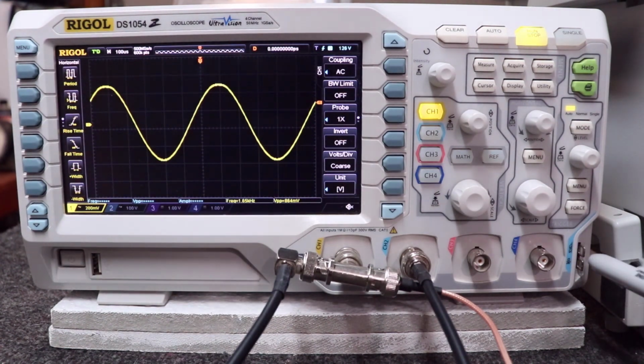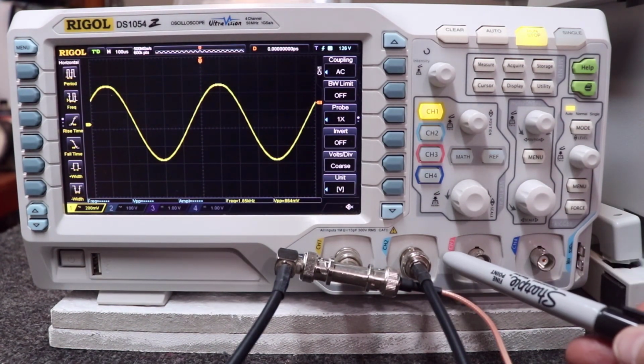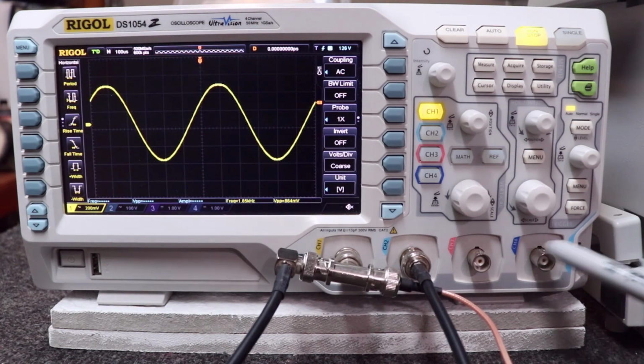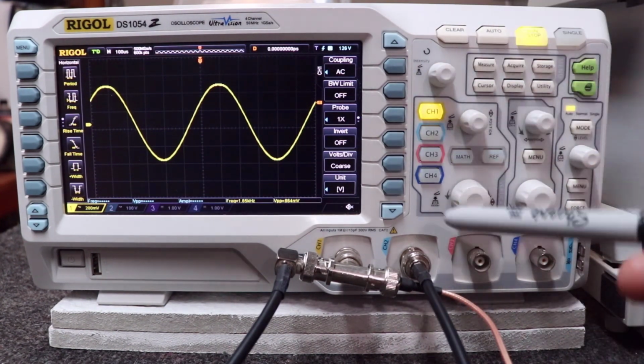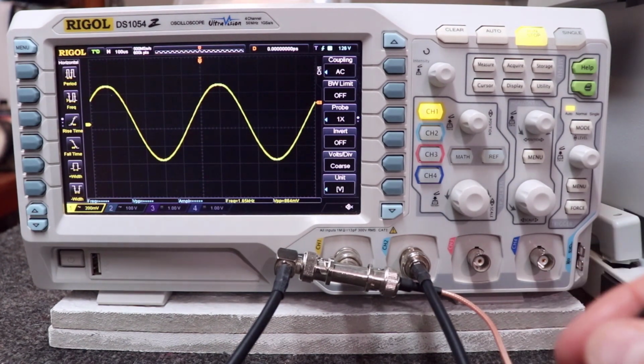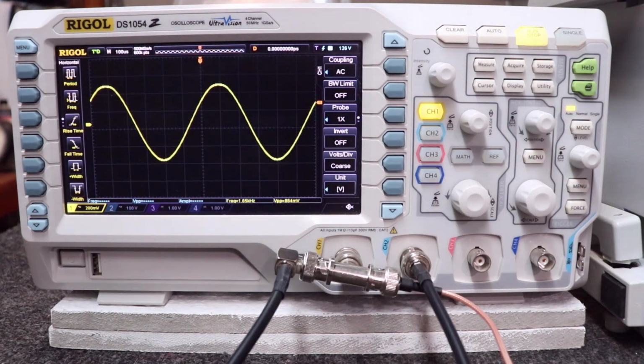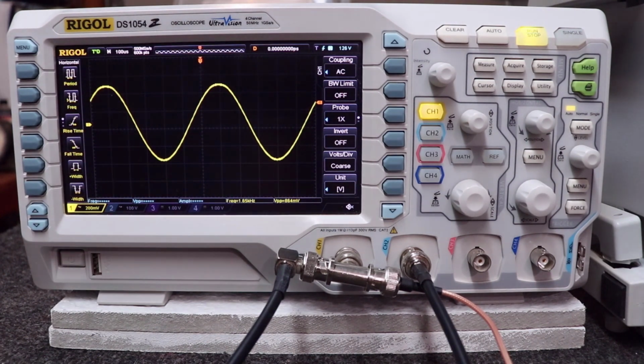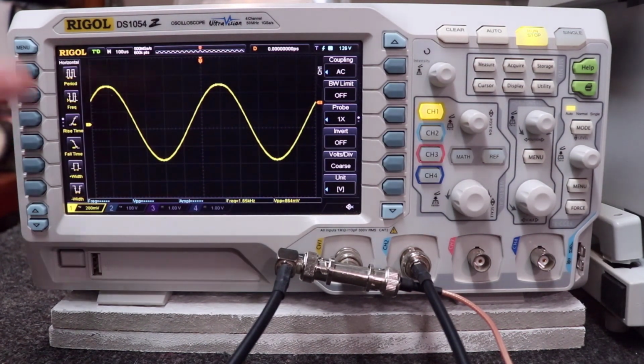And I failed to mention on the previous oscilloscope, it had a banana jack that you could have plugged in and tied the ground of the oscilloscope down to the ground of whatever you wanted inside the audio unit. And if you'd used some kind of device to isolate the ground, then you could have kind of floated that ground and tied it to the oscilloscope.